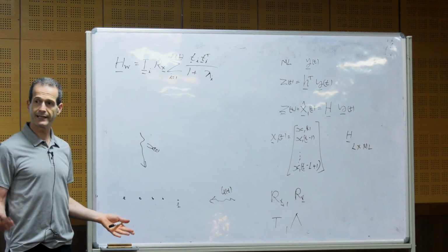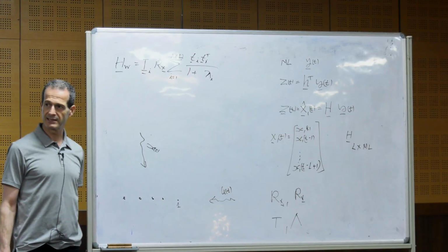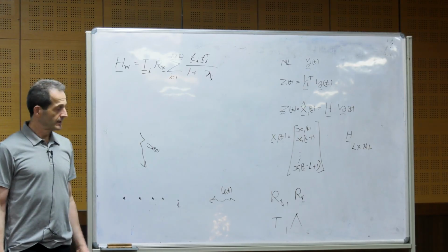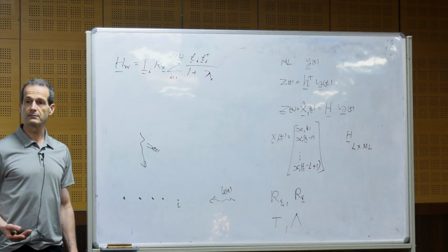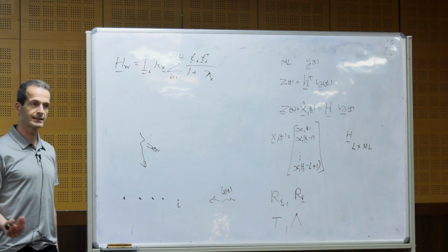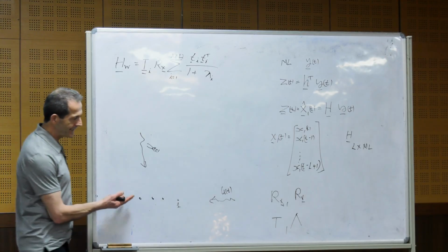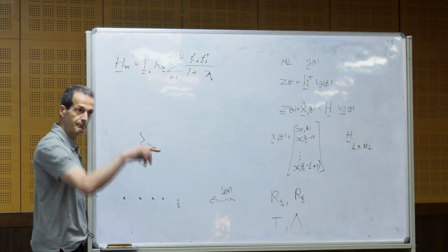Higher SNR. So I can reduce the thermal noise by averaging the signals. But if I have an interference, I can suppress it much better than just averaging. I can suppress it such that I get a null in that direction in the beam pattern.